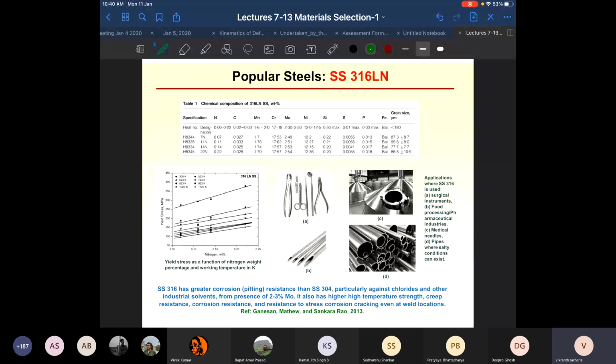No, no, no. Stainless steels are very tough and they have very good ductility. You can form them really well. Carbon percentage becomes important when you are welding stainless steel components. When you are welding, chromium reacts with carbon to form chromium carbide, thereby depleting chromium in the neighborhood of the weld. And the joints become susceptible to corrosion. If you use low carbon percentage, you reduce this chromium depletion around the weld zone. So it is for this reason that carbon percentage is very important in stainless steels.